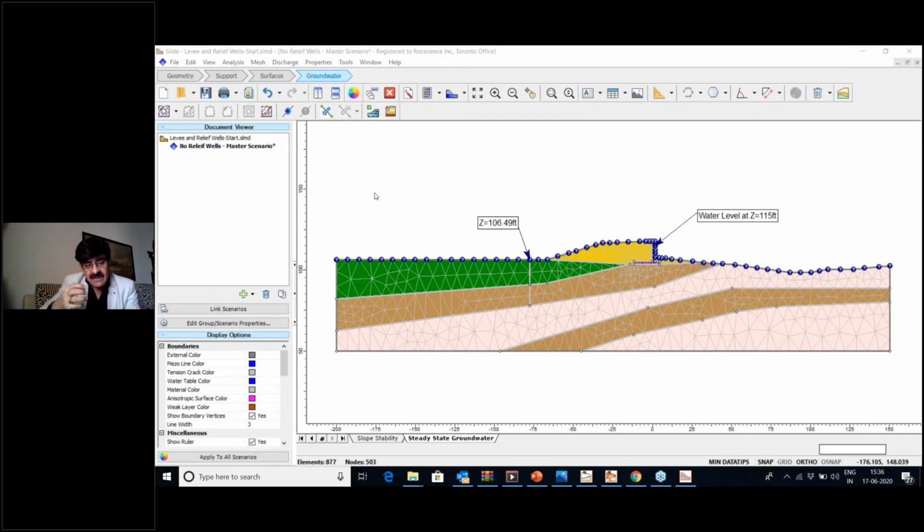So I will use a denser mesh in that area by using this option here, increase density through a window input. That's the window I chose. And you can see the mesh has become dense here. So more calculations will be carried out. We'll get more accurate information about things like pore water pressure, etc. in areas close to our area of interest.